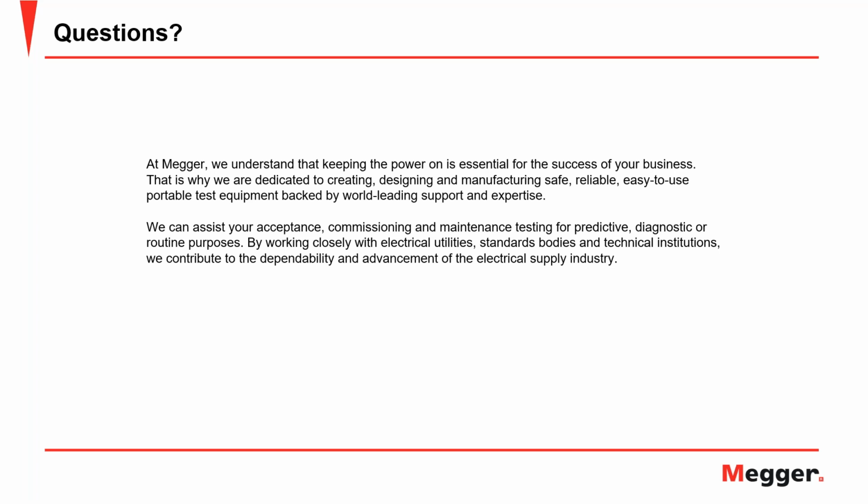Thank you, Dinesh. Ken, do we need to remove the bushing separately from the transformer to measure the C1 and C2? Thank you for the question. You do not need to remove the bushing from the transformer to measure C1 and C2. You will, however, need to remove that bushing tap that Sanket showed in one of the connection hookups for the Delta 4000.